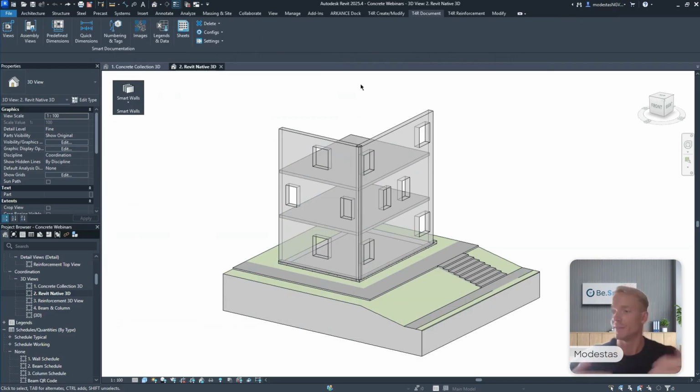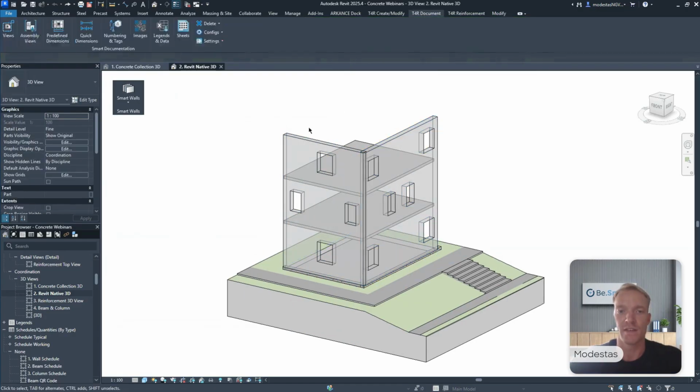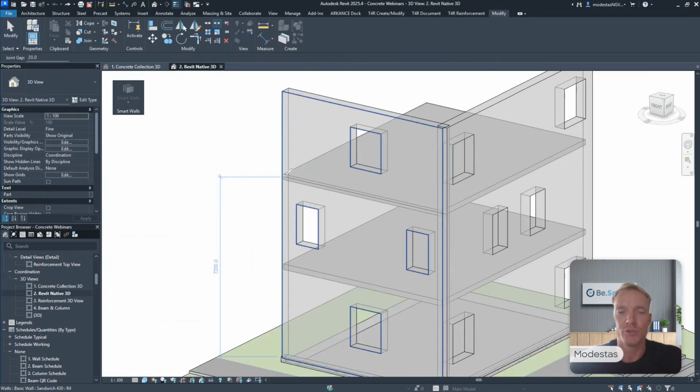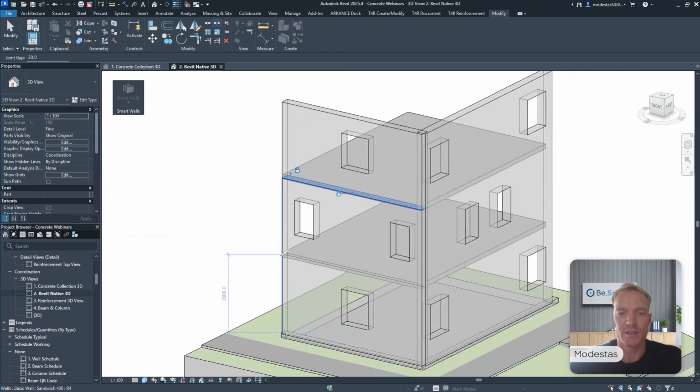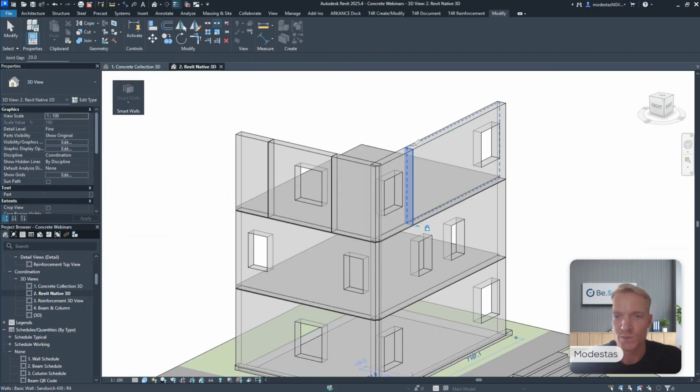and Revit native features. To begin with, I have modeled these walls like this, and I want to split them at certain distances, horizontally and vertically. For that, I can use Split Element or Split with Gap. I might be able to do horizontal splits more or less accurately. However, when I'm working with the vertical splits, the first challenge of the day comes into play, right? I'm not sure if I'm making those splits in the right positions.